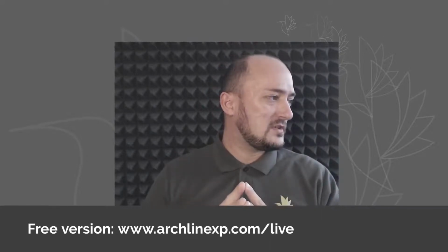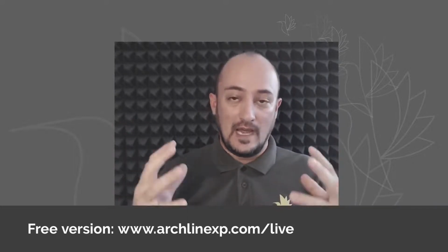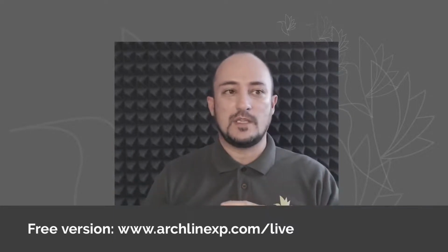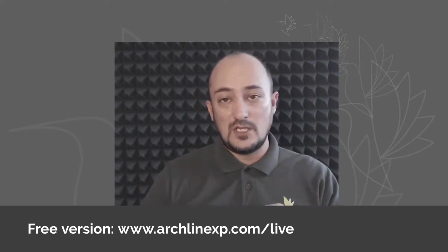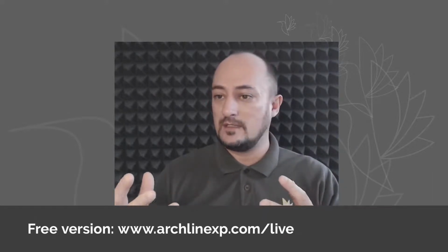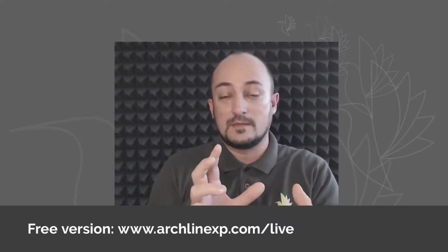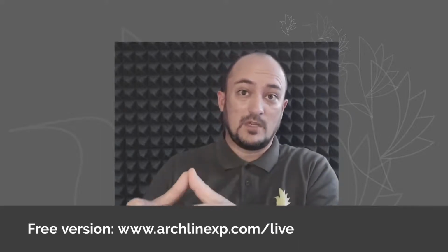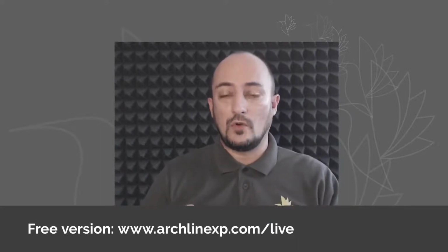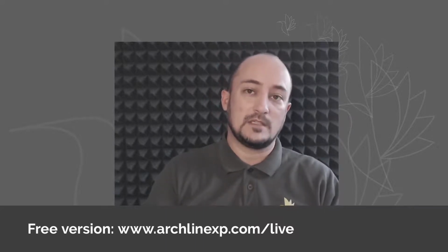Can I import an object as an XREF? Well, if you import something into Live, it is fully imported, so it's not referenced, it is imported. So if the model itself changes later, let's imagine that in this previous topic, if I change the SketchUp model of that smart hoover and I save it on my hard drive, then it won't automatically change the smart hoover itself, which was already placed in the model.